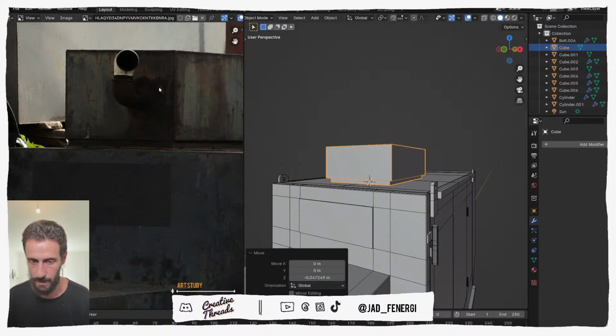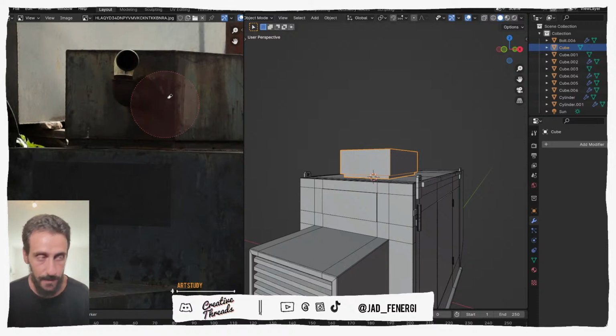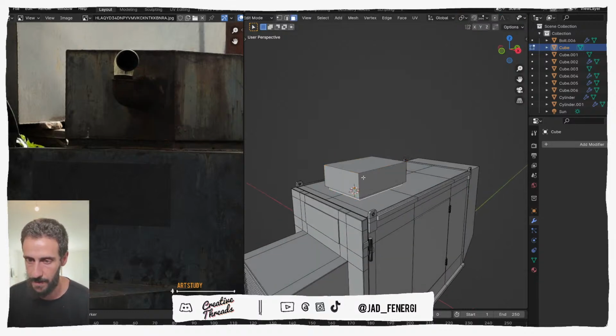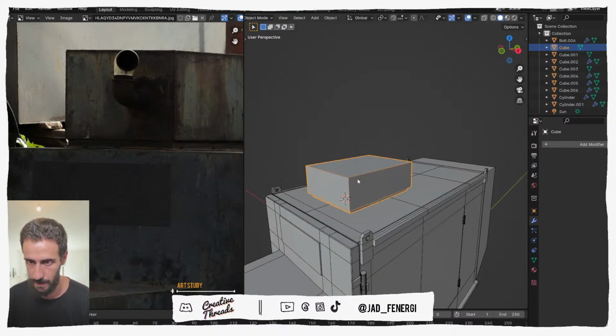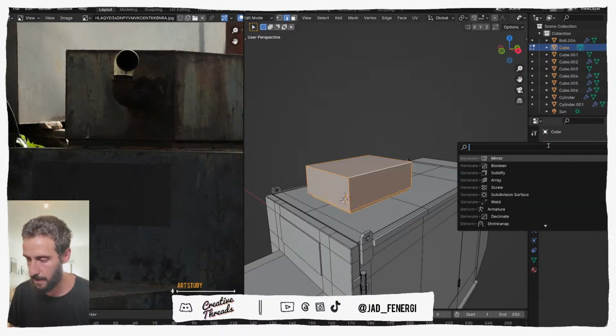This is one thing. Now we want to make the exhaust, which looks something like this, and then it rotates around. So we can do it in two parts, because it is two parts actually. But first, let me pick all of the edges here, I guess. It should be all of the edges for this guy. So press A to select everything, Ctrl B, or what we can do instead, we can add a chamfer modifier or a bevel modifier.